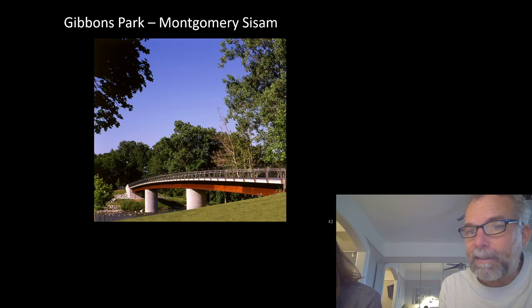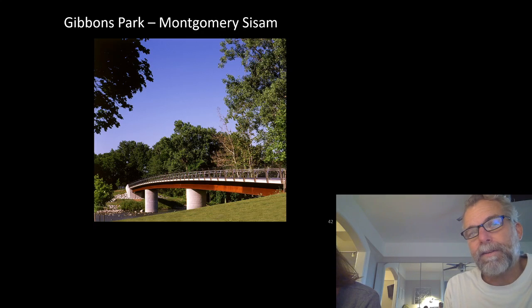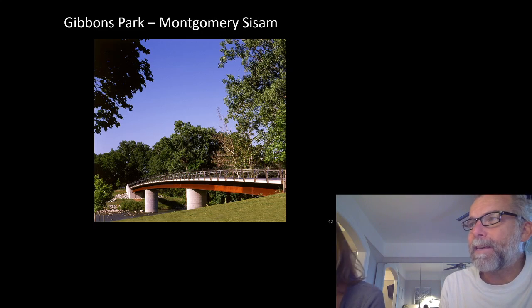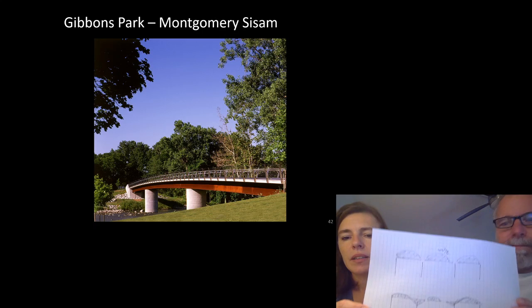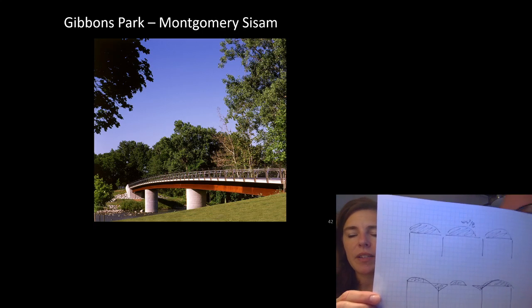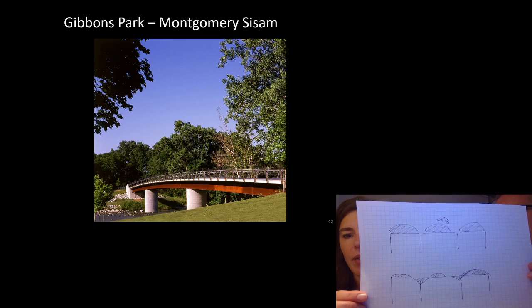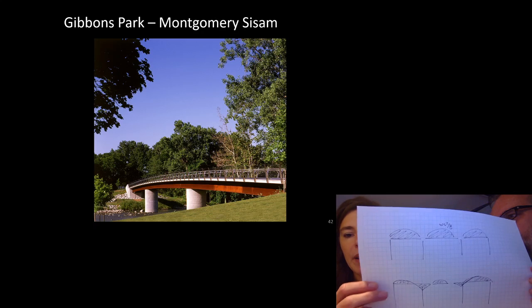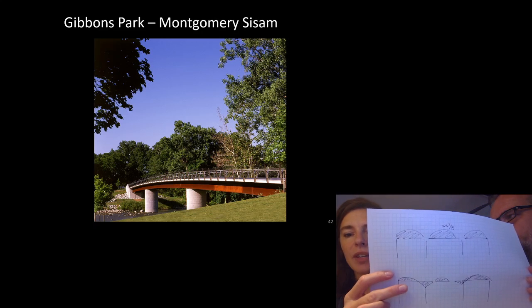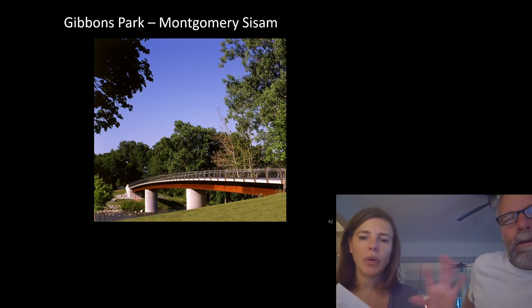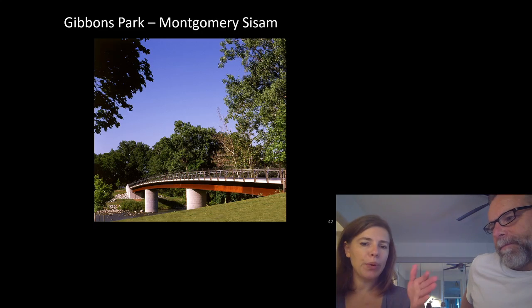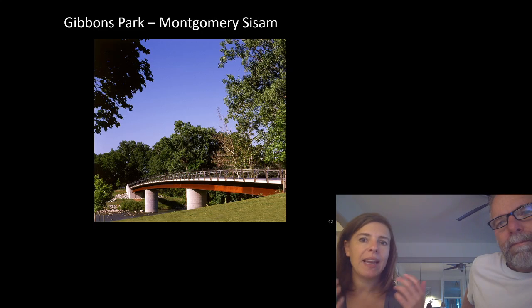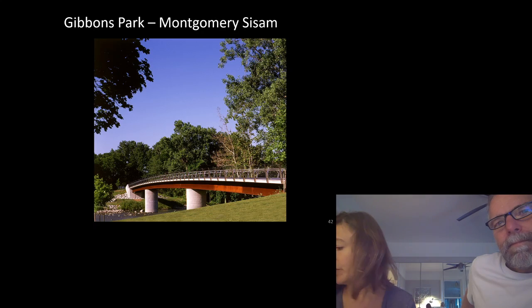The deflection, so that's the strength criteria. The deflection, I think, is about an eighth of the deflection that you would have. So the top one is our normal WL squared over 8 bending moment. You can see that we have it top and bottom, which means we have to worry about some lateral torsional issues. But on a bridge that's wide, those problems tend to go away, or they can easily go away if you make it a box girder section.